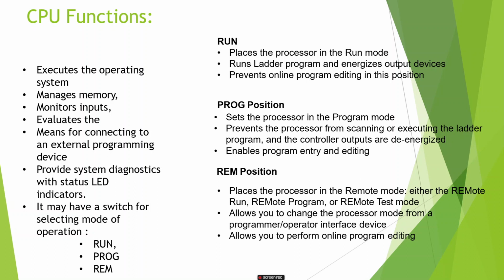In the run mode, the processor is placed in run. It runs the ladder diagram and energizes the output devices. And during the run mode, it prevents online program editing in this position. You cannot edit the program online.